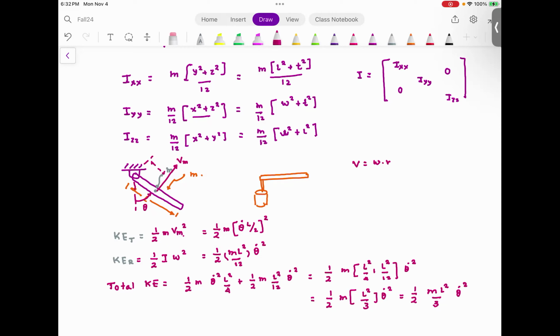Since the mass is distributed across the length, it will also have the rotational kinetic energy. And rotational kinetic energy is given by 1/2 I times omega square. Yeah. So can't we just take the I from the pinned edge and you will directly get this thing? Correct. That is absolutely possible. But you can only do that when it's a slender rod.